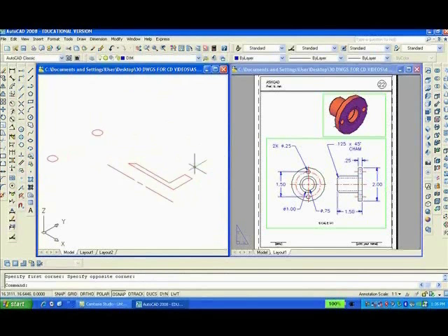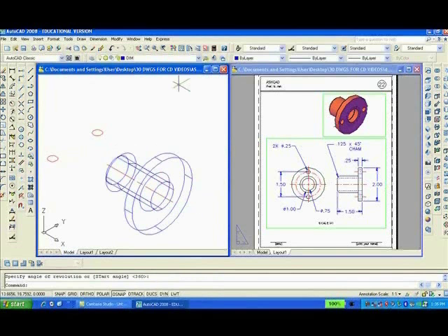So I'm going to type REV, enter, revolve that around this axis, 360 degrees. Okay, now I'm going to extrude, EXT, enter. These, any particular height, it doesn't matter. Extrude, height, make it 6.